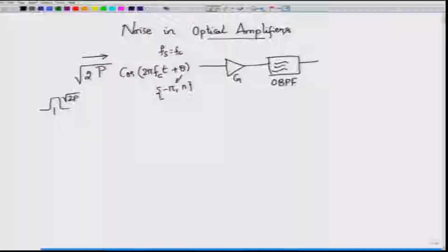After you have filtered in the optical domain, you put this through a photodetector, so that you may convert the optical signals into electrical signals. You might also want to put up some electrical filters here in order to limit the out of band noise, or the electrical filter could be part of the transimpedance amplifier design that goes with the photodetector itself. What you get at the output would be the photocurrent that you are interested in. The filtered photocurrent is what you are going to get, and whatever processing you want to do, you can do onto this photocurrent. So, this is our model.